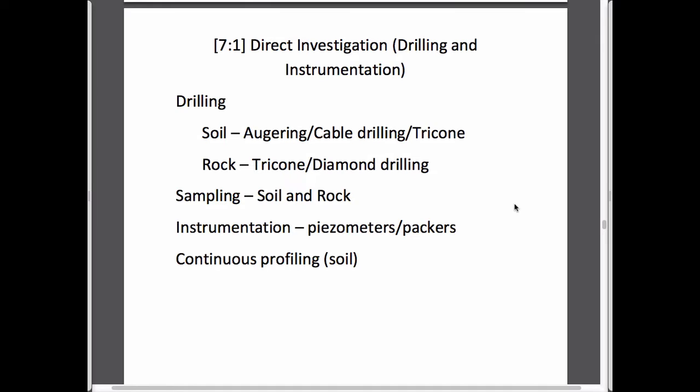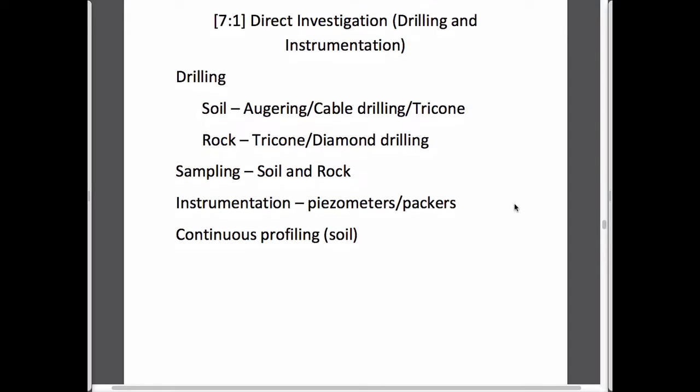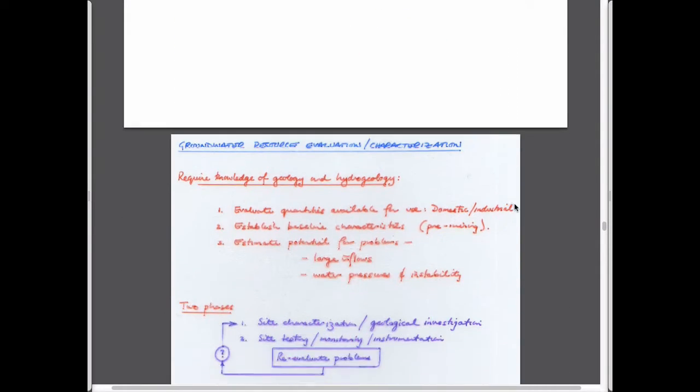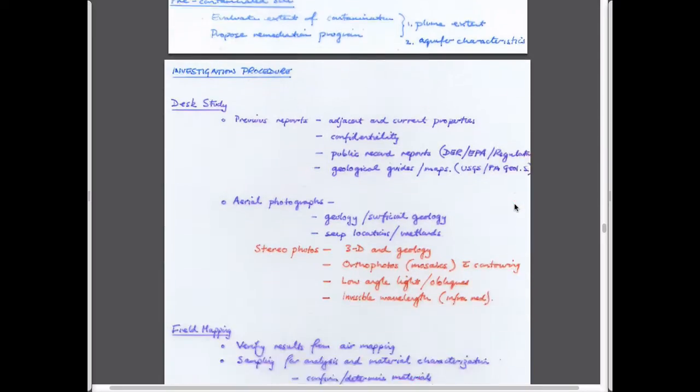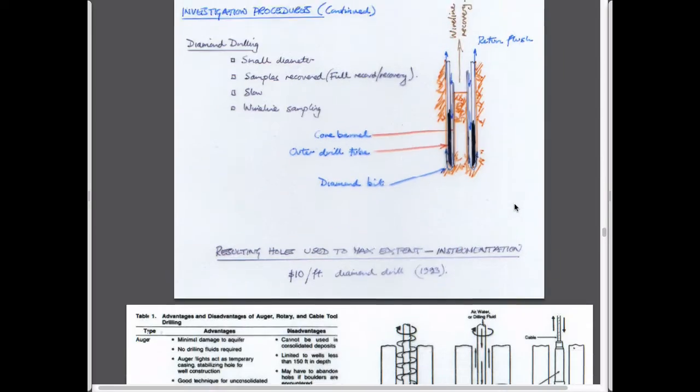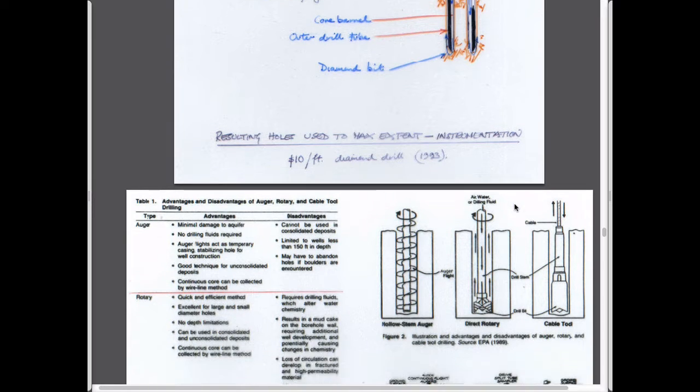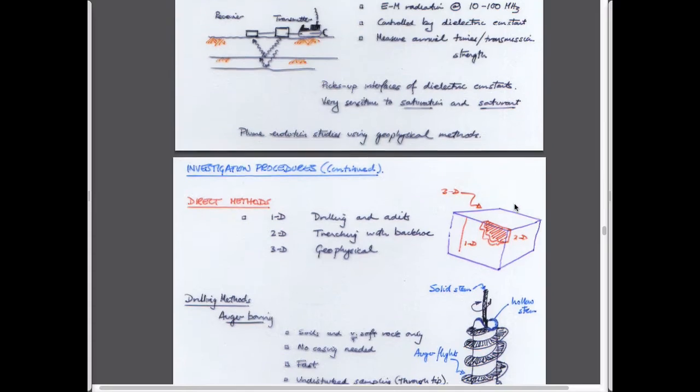If you drill and sample, most of the cost is for the drilling part, and you're left with a borehole or a well bore. It's often crazy to not utilize that and to put in a well or a piezometer that can give you information other than the things you've removed from it. And so the first part of our discussion is talking about profiling. Now, I don't want to go through everything that's in here, but I'll zoom in on a variety of different modes.